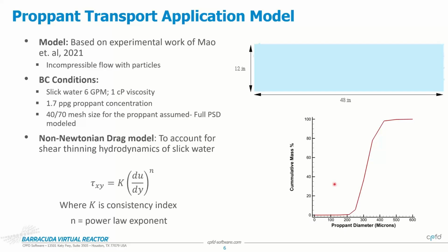And then the other key point is just the liquid itself. As I was mentioning, this is water mixed with some sort of polymer. So this acts as a non-Newtonian fluid, and therefore the shear stress is not linearly proportional to your strain rate. To account for that, we use a power law model. Generally, for shear thinning fluids, n is less than 1, and we define this as a user-defined model inside the setup. I'll touch upon that when I open up the software and show you where it is. We also provide some instructions or description for this on our website, which I'll highlight.